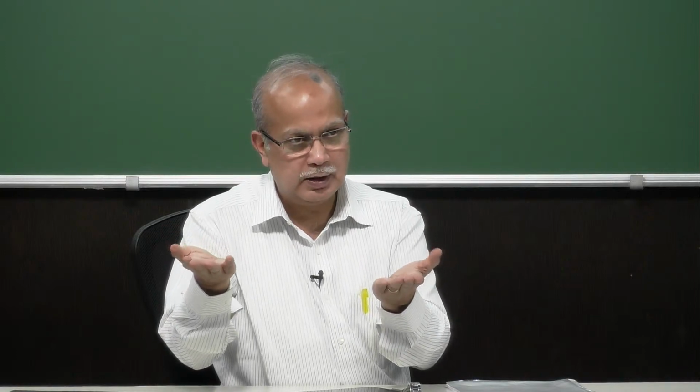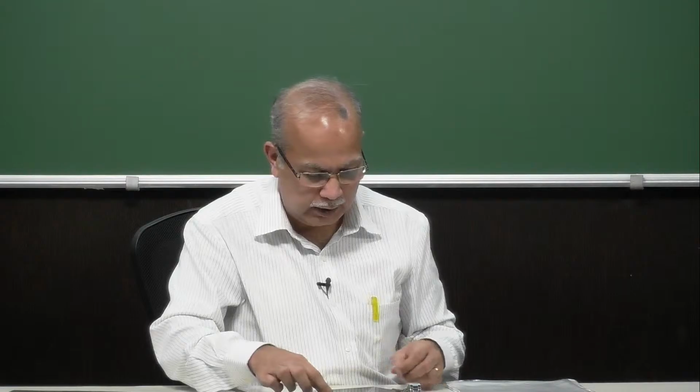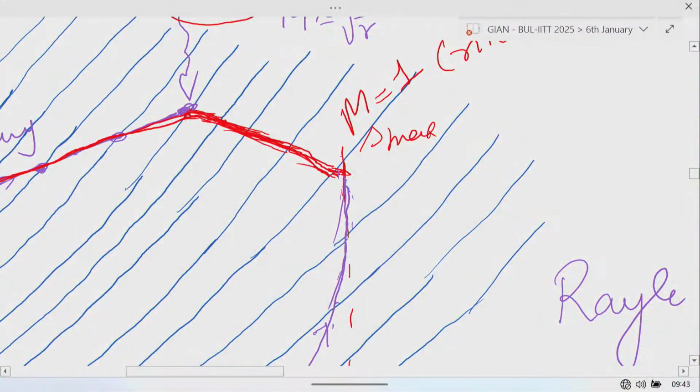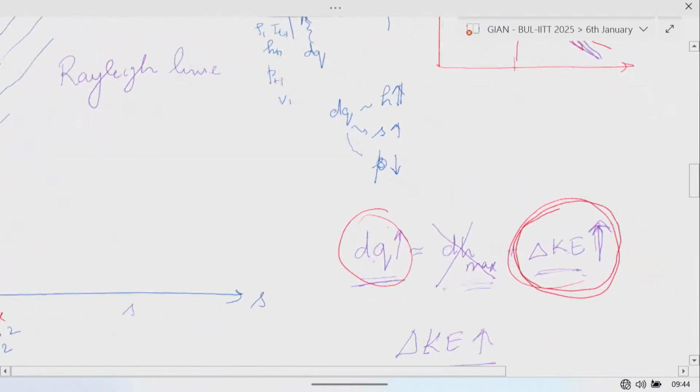So it takes energy from the flow, and that's why we see that the red line is dropping. So from here, it is giving off this energy, so it is losing its energy, but the flow is accelerating. And then the flow is accelerating and reaching the critical point, M equal to 1. That is how we see from this energy equation here.